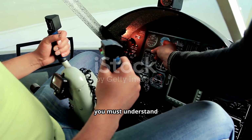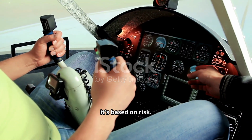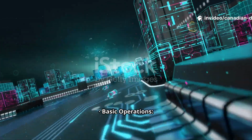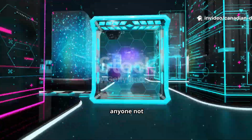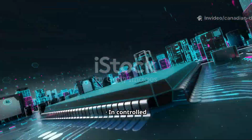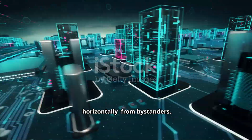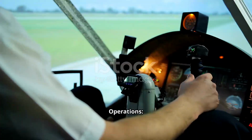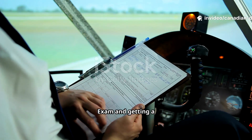context. First, you must understand which set of rules you're flying under. In Canada, it's based on risk. Basic operations, lower risk flights. You cannot fly over bystanders, anyone not associated with the flight, in controlled airspace, without permission, closer than 30 meters horizontally from bystanders. Advanced operations, higher risk flights, requires passing the advanced pilot exam and getting a flight review.